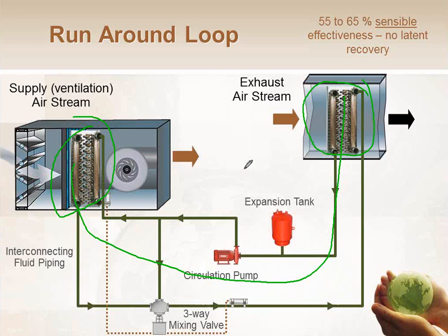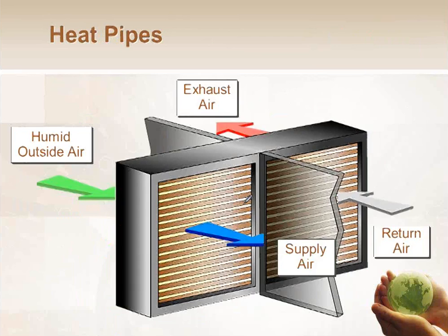However, you can do absolutely no latent performance with this. This is a sensible-only thing. It can preheat and pre-cool, but it can do nothing in terms of dehumidification or humidification, right? I guess unless you get a hole in your coil and the water leaks out, then it might help you humidify. But you definitely don't want a hole in your coil, right?